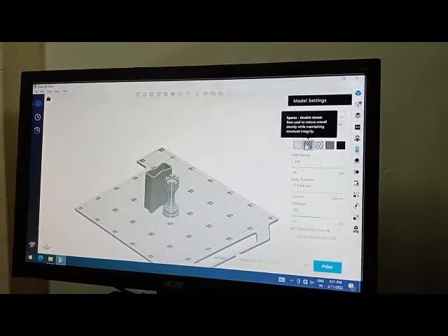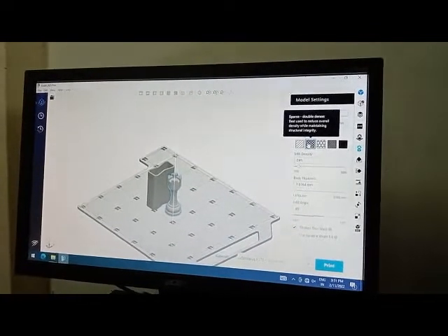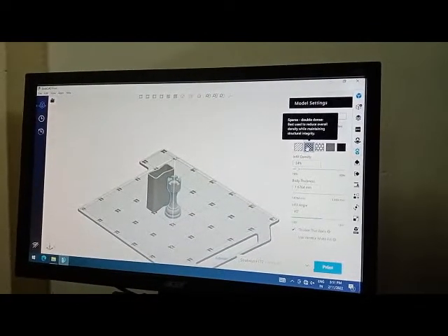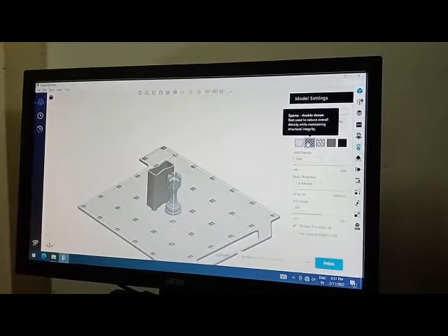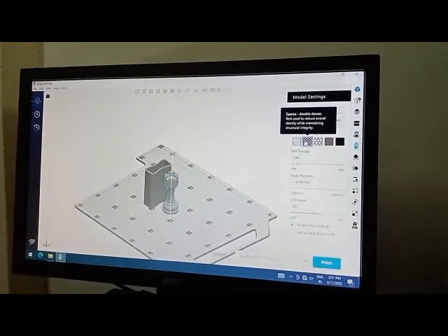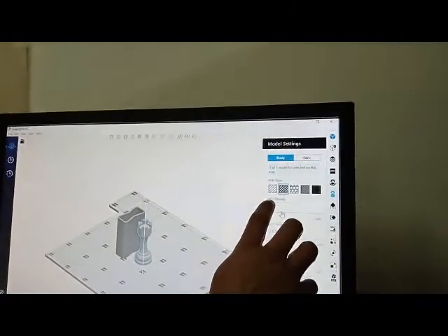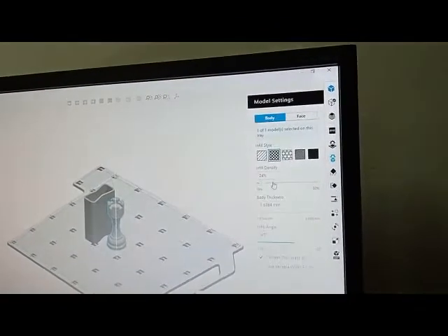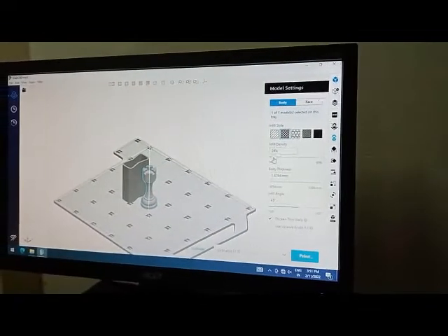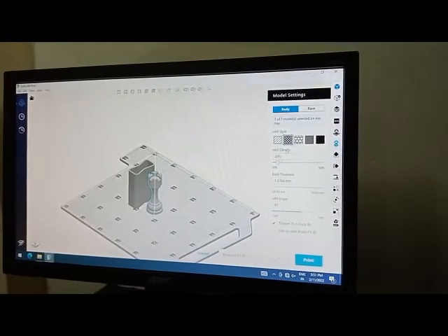We have some nominal forces on our part, and we don't want the density to go very high. We don't want 100%, or 50%. So we can select it. After selecting this, you can see infill density automatically becomes 24%, and again we can change this. Fine, so let's keep this one.